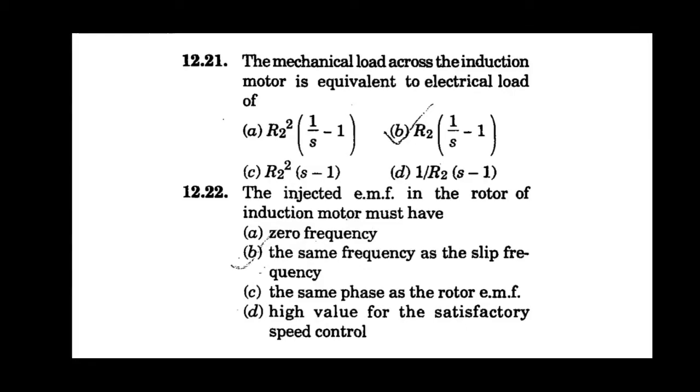The mechanical load across the induction motor is equivalent to electrical load of R2 into 1 over slip minus 1. The injected EMF in the rotor of the induction motor must have the same frequency as the slip frequency.